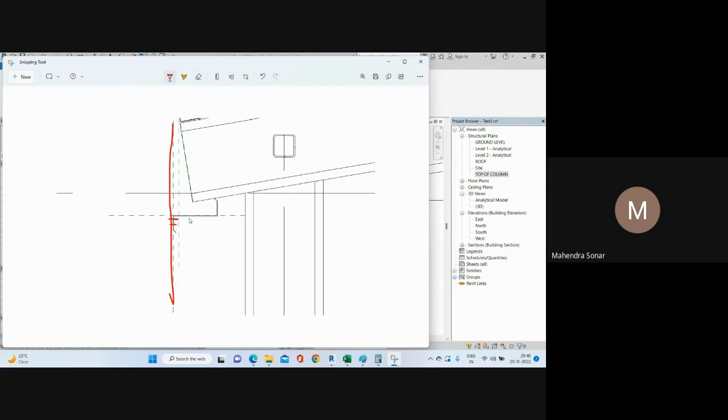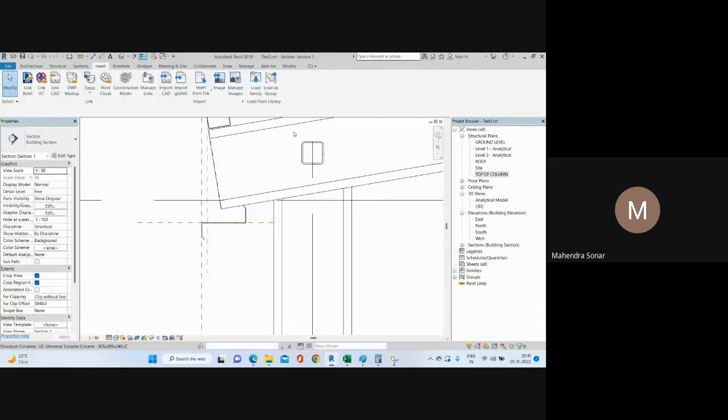Then in that case I want to make this plate longer, like that. Then I want to add the bolt here, or you can just increase the size. If you don't want to extend, or as per your design this plate does not fit at this distance, you can extend or you can increase the size for the Z side purlins.